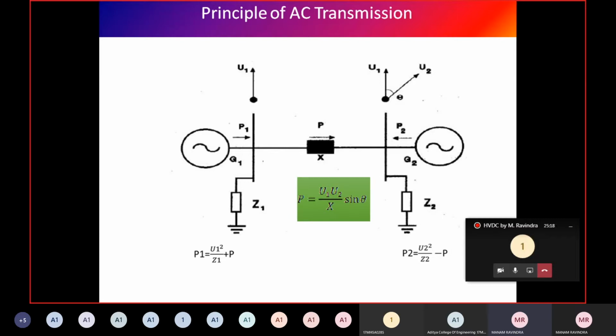That is the opposite case in distribution lines. Is it audible to all of you? Hello? Is it audible? Yes, okay. Here in distribution lines, the X by R ratio will be very low. How can we say this? As the conductor size of the distribution lines is very low compared to the transmission line, the cross-section area is very less, so R, which is directly proportional to rho L by A, will be very high. That means the X by R ratio will be low.